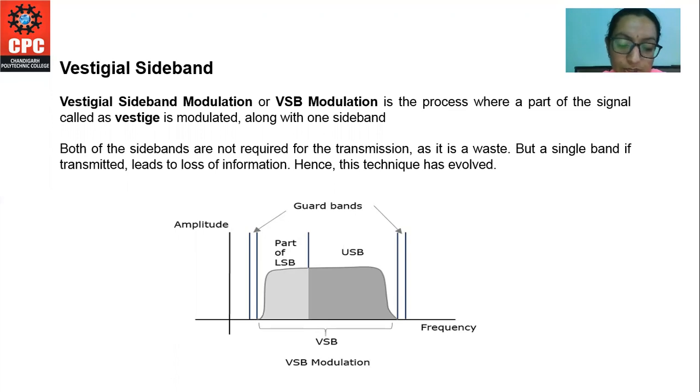Some major advantages of a single sideband are bandwidth saving and power saving, which enables its extensive use. With the use of SSB, some demodulation complications arise, as opposed to the AM system in which the carrier is also sent. The larger the bandwidth required by the signal, the larger the spectrum space. Spectrum space can be saved by transmitting only one sideband instead of both.